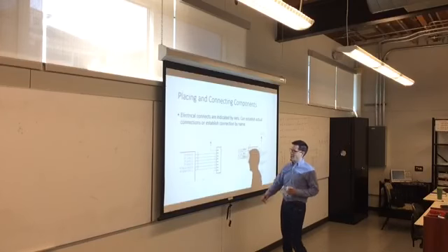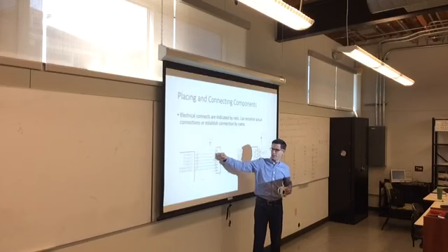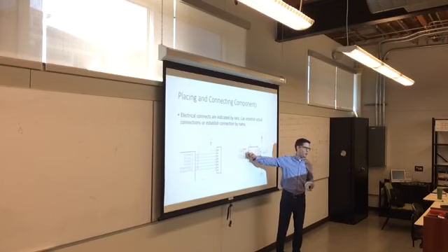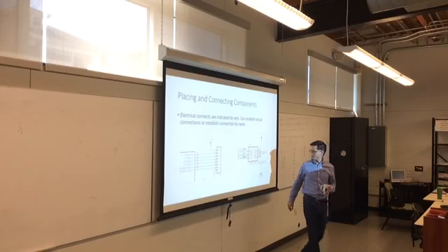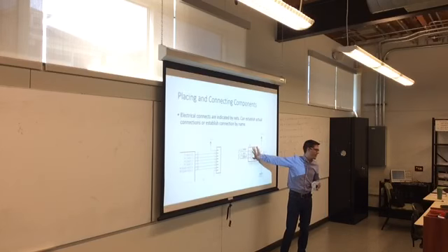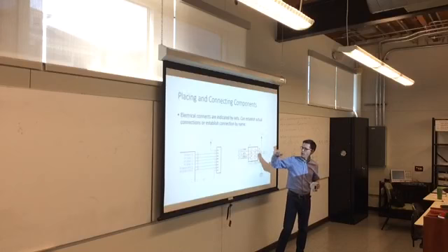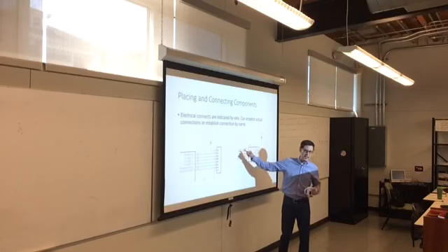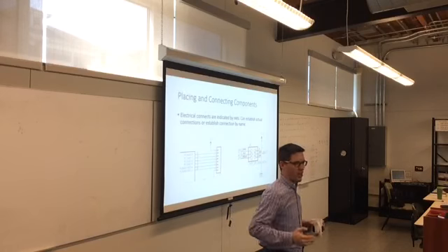And the reason that you use a net is that you can say go from this pin to this pin, but you can also label the net, and everywhere you have a net of that label, it will be logically connected. So this is the header programmer for Atmel. This is the ISP programmer, and this is connected to the MISO line on the SPI interface. You'll notice that there isn't a line here running all the way back over to the processor, because that would make a really ugly schematic.